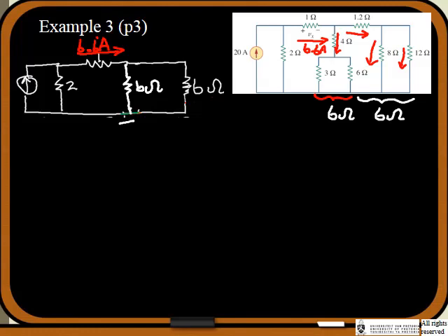Right. So first I need to figure out what are these two currents. On this board, it's the equivalent of that current and those two currents. What are those values? Let's just erase these two so that we know which two currents we are working with. So these are the currents that we're working with now. That 6.6 has to divide itself between a 6 ohm and a 6 ohm. Now you're welcome to go and do the current division, but if we just use a little bit of logic, if the current has to divide itself between two of the same size resistors, what's it going to be?